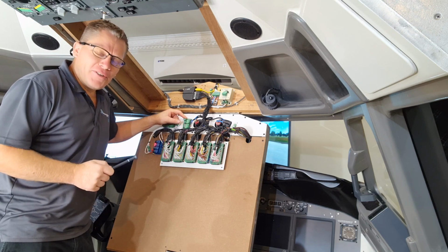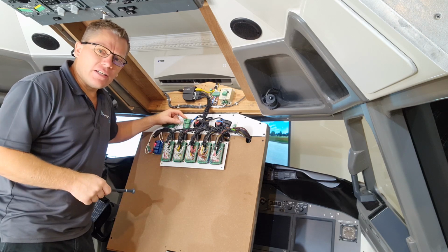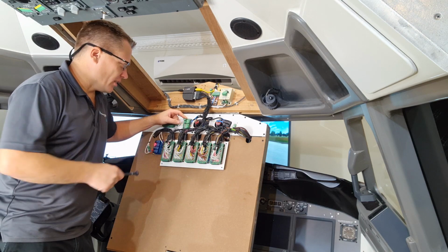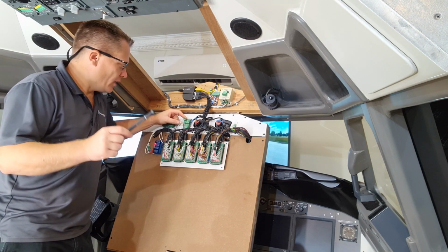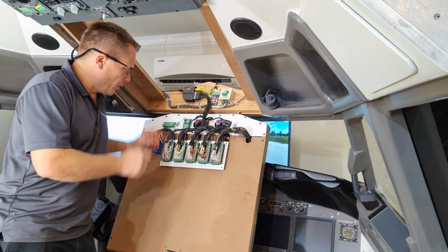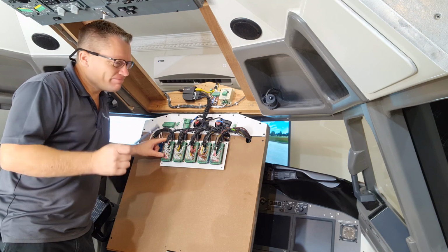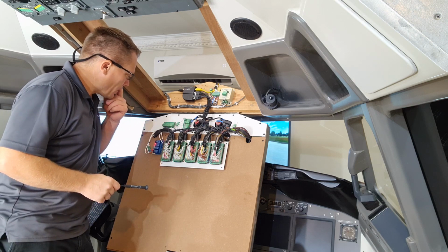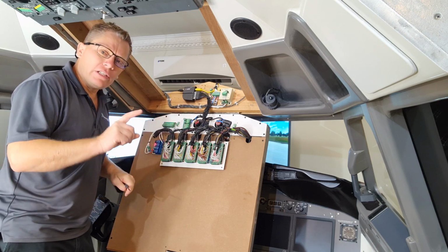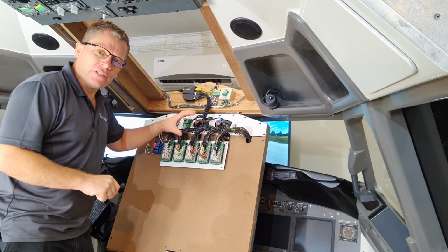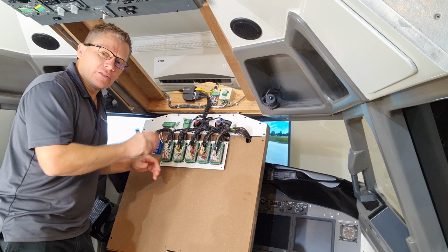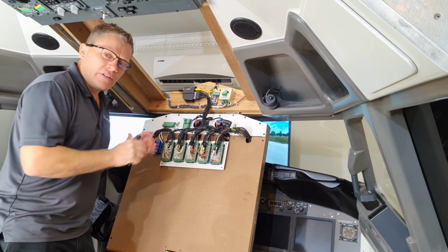I thought it may have just been a fluke, so naturally I replaced the fuse in the 12-volt system, and then restarted again. Same thing happened. The fuse didn't blow, but the Arduino blanked out and the computer restarted. It was only when I released the solenoid valve that I had issues. Getting them to operate was fine, but as soon as I let the solenoid valve go, everything started to shut down.